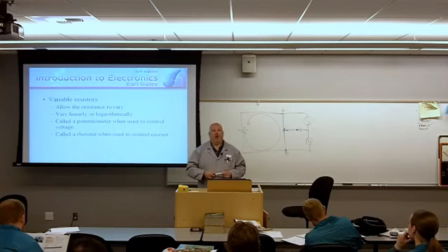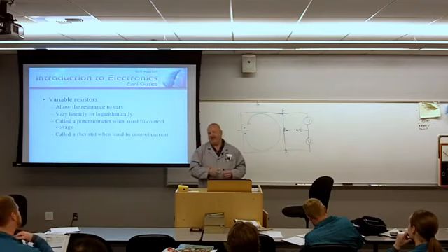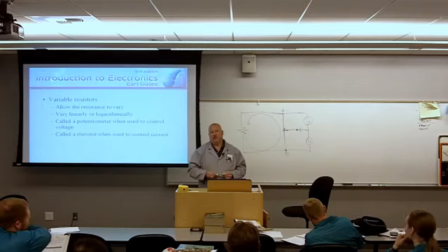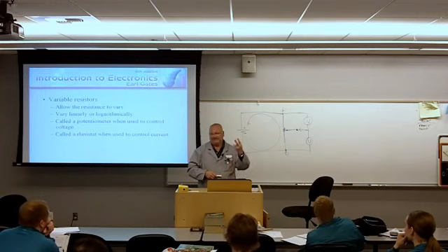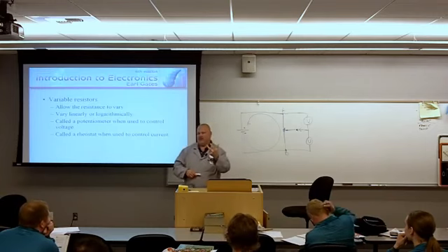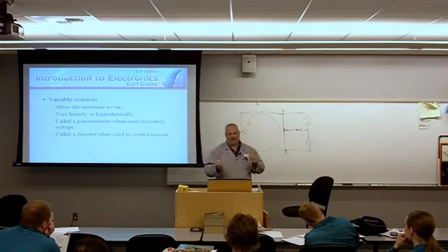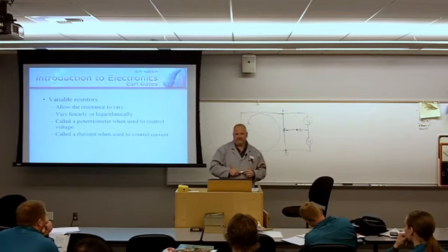If you went out and special ordered a rheostat, and it came in the box and it said rheostat, could you use a rheostat as a potentiometer if it only came with two terminals? No. You need that third terminal to be able to divide the voltage. Make sense?